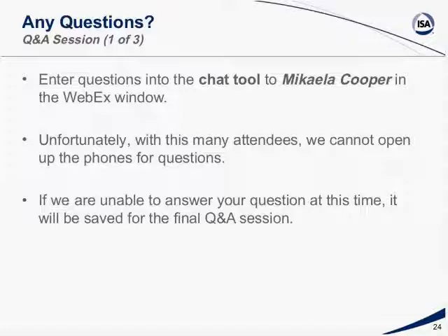You're typically going to have a lot of things coming in, a lot of different alarms. So if you have a digital or whatever that actually shuts the plant down, that really doesn't need to be alarmed because you kind of know you just shut the plant down. Now, you want the other alarms for troubleshooting purposes, first outs or things like that, so you can diagnose why you shut down. But having an alarm on a point that shuts you down is not necessary because at that point in time, there truly is no operator action other than maybe to initiate some emergency response procedures. But once again, the operator will already know the unit is shut down because of everything else that's screaming at them on their HMI.